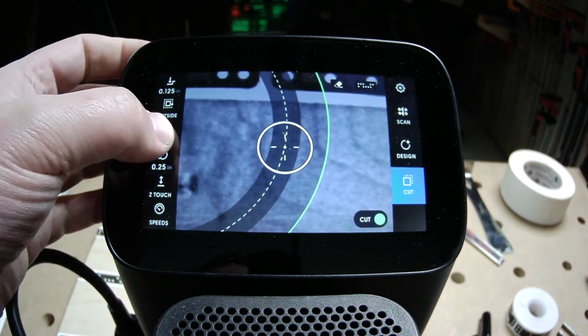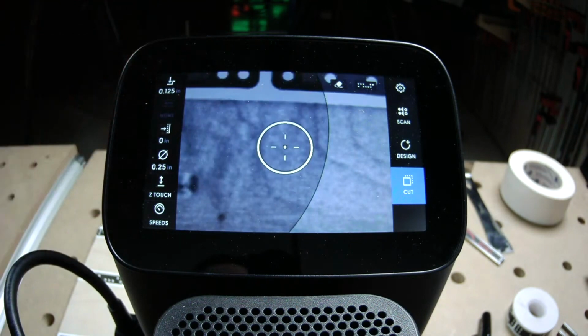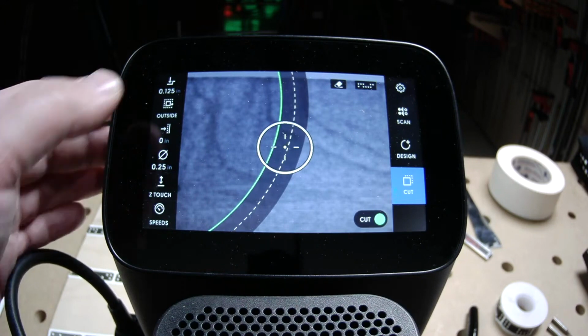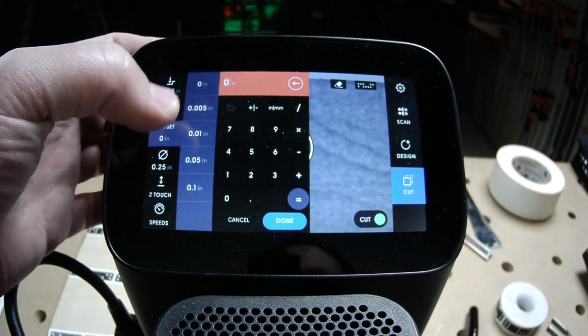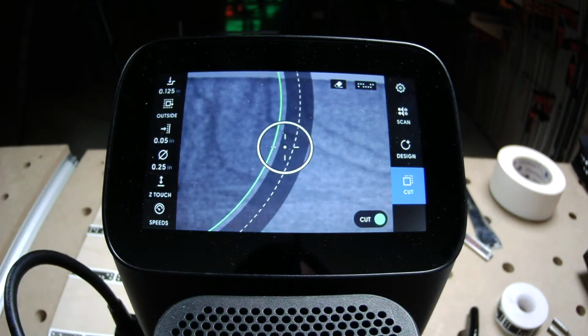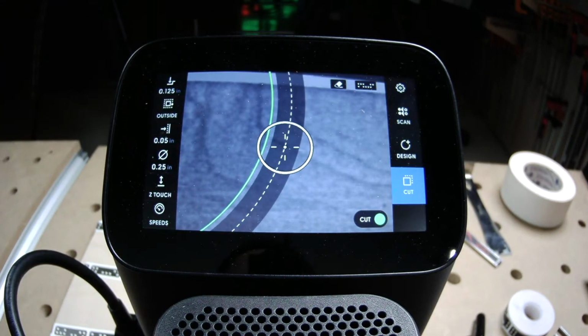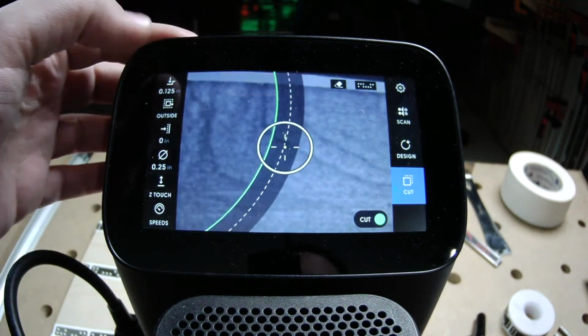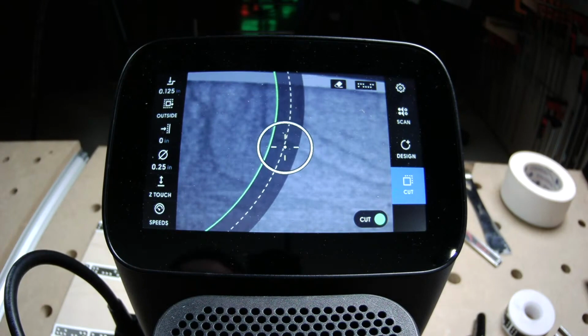So offsets, we talk more about offsets in a lot of other sessions, so go back through the archive, especially in joinery. Offsets are really important for dialing in fit, but also just when you're cutting generally, I like to do a rough and finish pass. So I'll generally put like 50 thousandths of an inch offset, do my depth passes, and then on my last and final pass, I just go to 0, and that gives you probably the best edge quality that you're going to get, just because you're not going to leave witness lines at every depth that you cut.